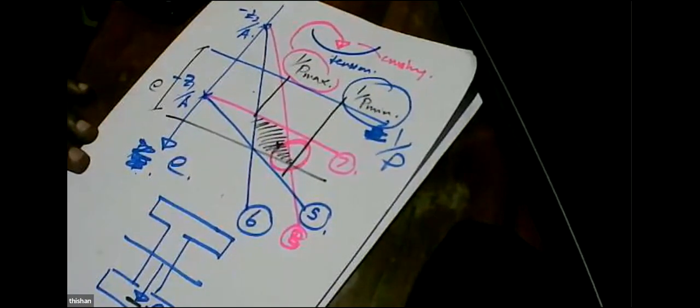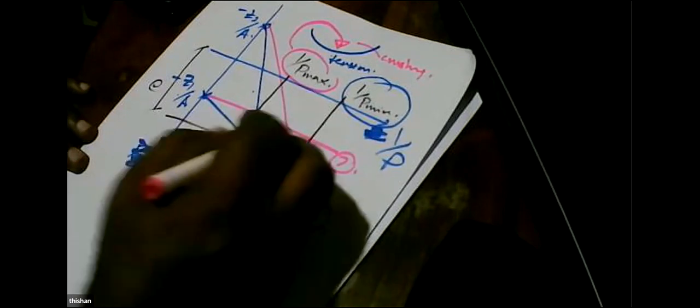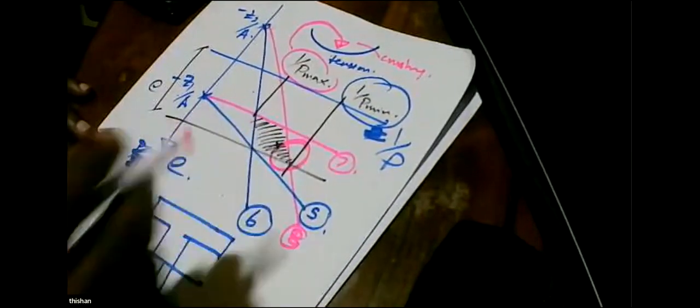It should be as low as possible. So that's the reason why, when you draw this diagram, not using equations, you can straight away say in which region we should be selecting the pre-stressing force.